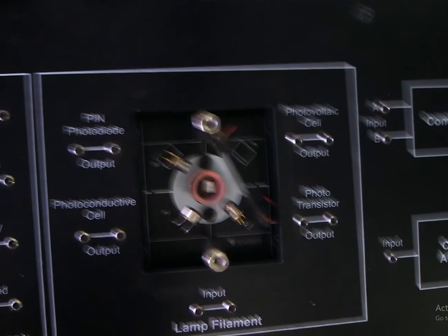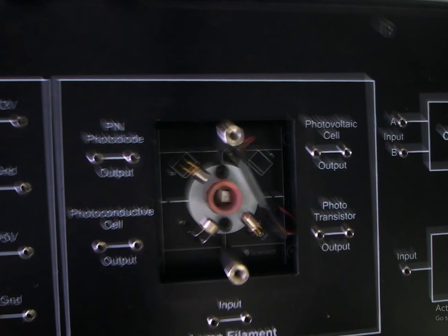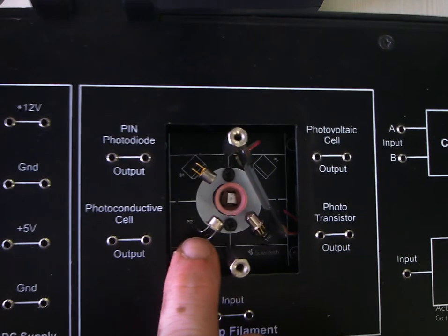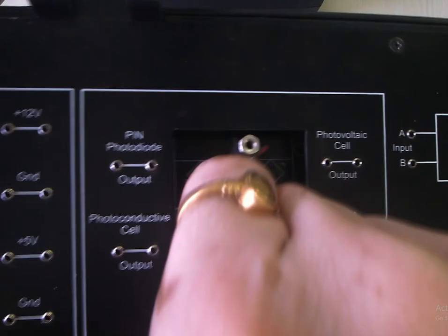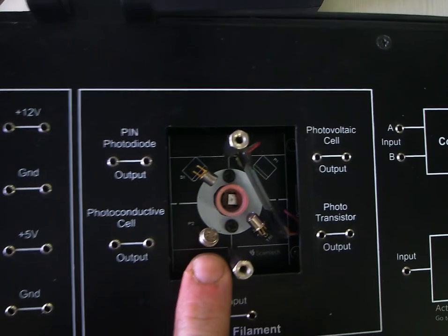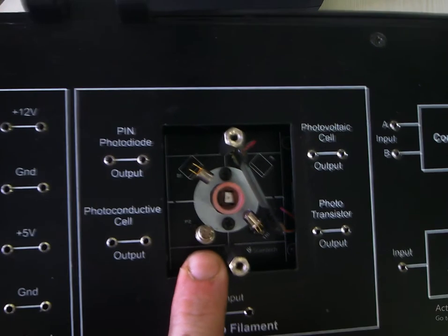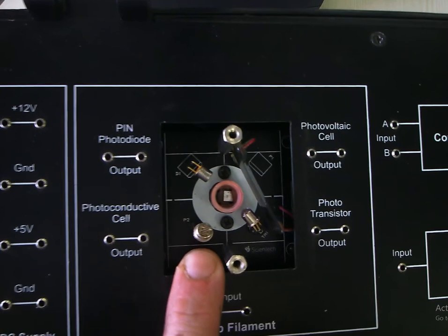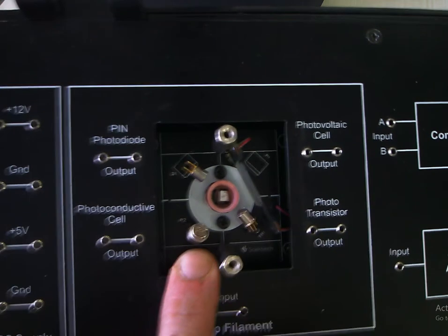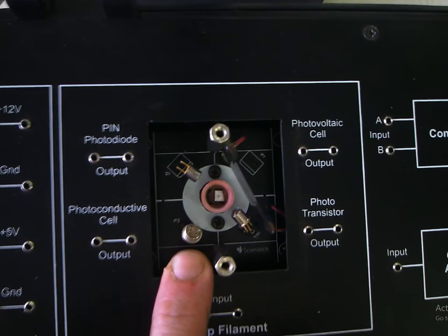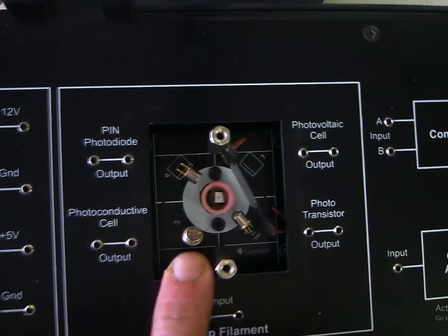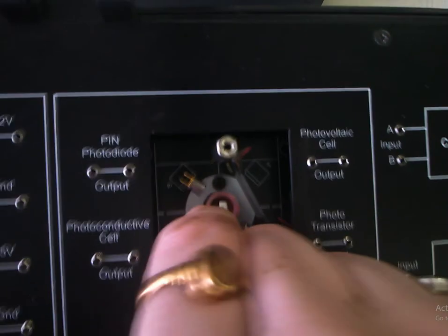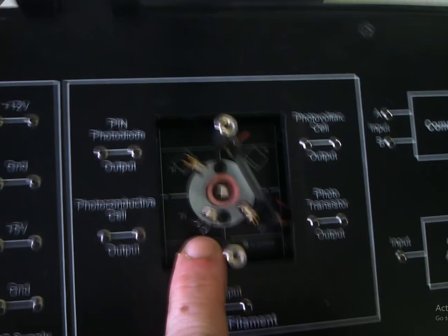Now see, next, this is the photoconductive cell. You can again find this is simply an LDR. In photoconductive cells, what happens actually is that when light falls on them, their resistance decreases drastically. Normally the resistance is very high. You can see here there are two terminals only.